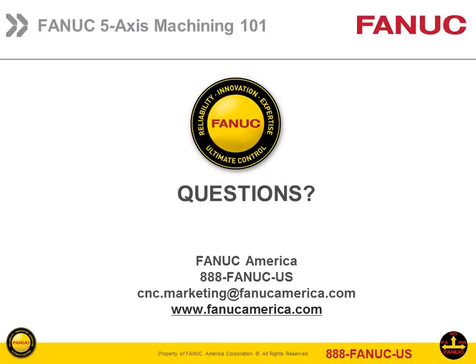Okay. Another one of our listeners wants to know, how do I activate tool posture control, and what does the program line look like? Again, that's the same thing that I just went over, but it's a G43.4 with an H word, and then the P word actually turns on the posture control. So, the same thing. And then you control it with vectors of the tool.